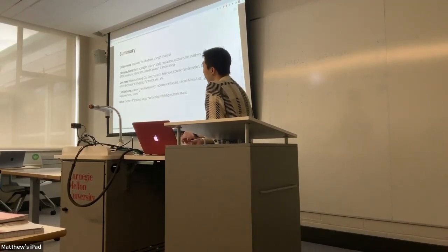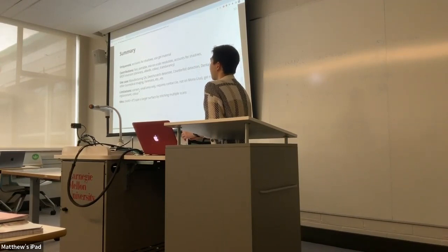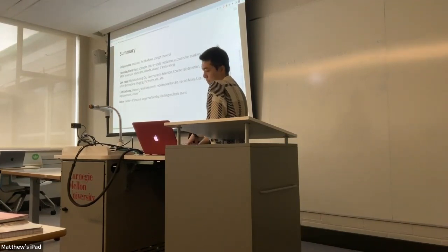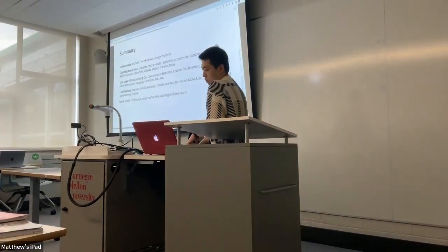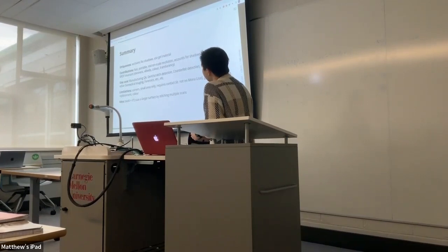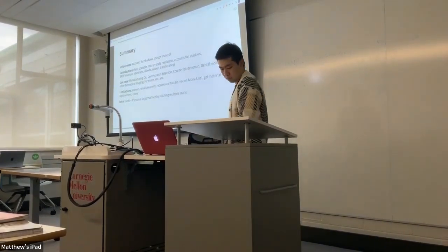One thing I think is cool that people have been doing is to add texture to the GelSight panel. So what we're seeing in this version is changes in the surface of that texture, right? It's a kind of photometric stereo approach where we're looking at different normal orientations. But there's more to the deformation of that surface. It's not simply the surface going up along the Z direction. Things can potentially shift laterally.